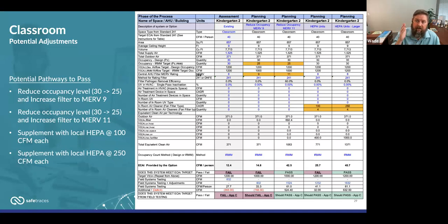But in the in situ test that's done this way, you're getting the full effect of outdoor air plus filtration plus whatever. Now understand, that's equivalent. If you buy an in-room fan filter air cleaning system that has MERV 8 filters or MERV 9 filters and other technologies, they test that entire system as a whole, and those components would also count towards it. So I just want to make sure that it's not some sort of adjustment or sleight of hand. It truly is the same that we're treating the other air cleaning systems when they're tested as a system. And that's what we're doing with this, is we're testing this as a system in the space. So that's the classroom example.